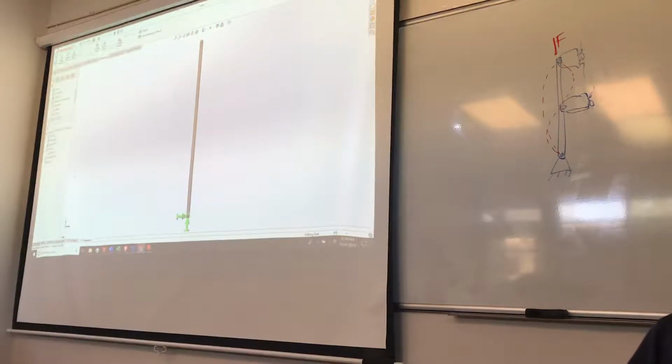Then we're going to put a load on the top, up here, and we're going to define it from someplace convenient, like the top plane. Then we're going to assign it out of plane, and make the arrow real big.